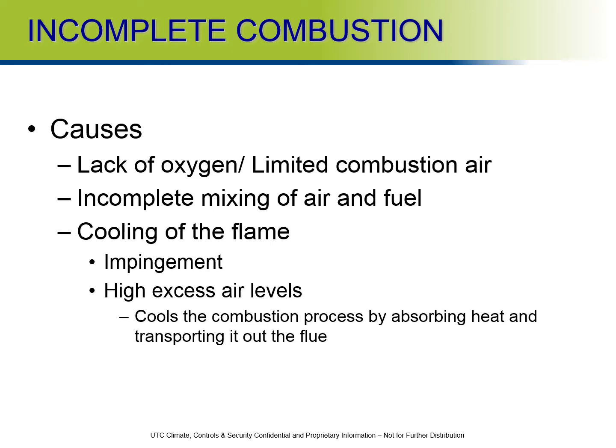All right, and then the next thing: cooling of the flame, flame impingement, high excess air levels. That cools the combustion process. So a good reference point here would be a cracked heat exchanger. A cracked heat exchanger will allow excess air to enter the combustion chamber through the heat exchanger from the blower, therefore impinging the air-fuel mixture of the flame, which will also create an incomplete combustion atmosphere.